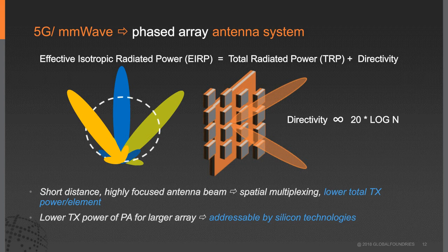As we go to millimeter wave, the antenna dimension shrinks, and the power levels transmitted by each antenna element reduce drastically. This happens because we are concentrating all the power or energy in one direction instead of the wide beam that you have in a typical antenna.